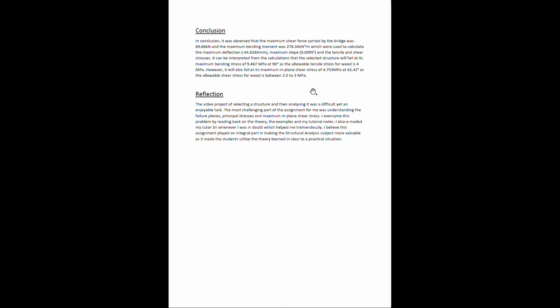It can be interpreted from the calculations that the structure would fail at the maximum bending stress of 9.467 MPa at 90 degrees, as the allowable tensile stress is only 4 MPa. Or we can also say that it will fail at maximum shear stress of 4.753 MPa at 42.42 degrees, as the allowable shear stress for wood is between 2.5 and 3 MPa.